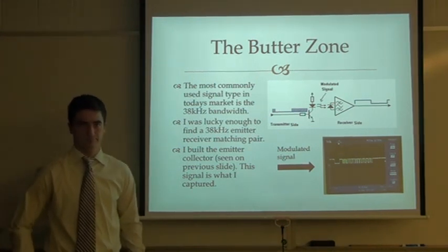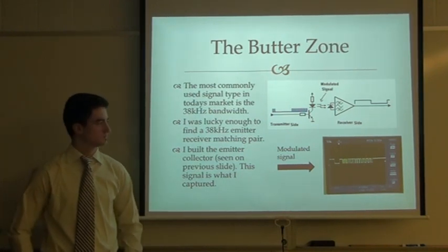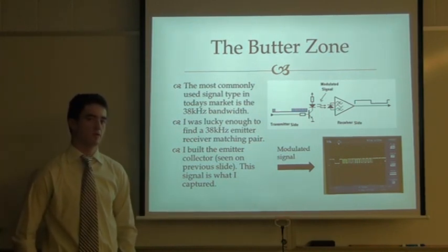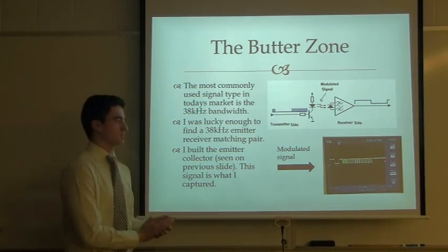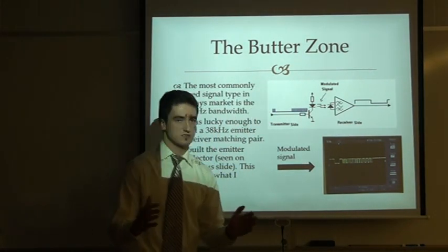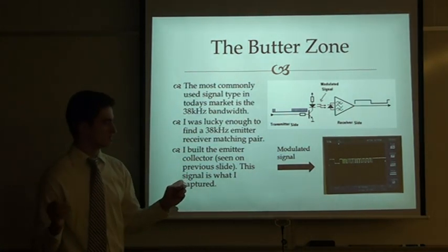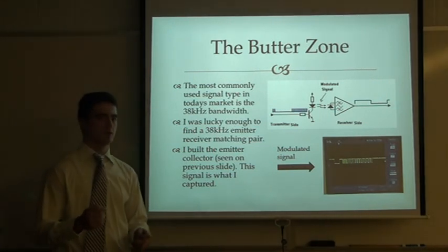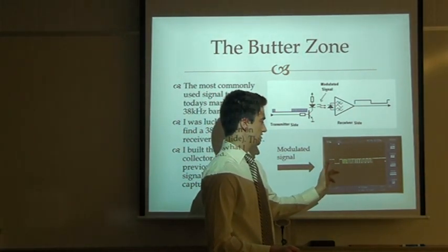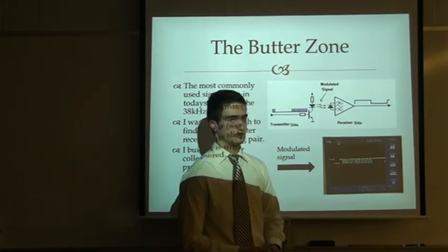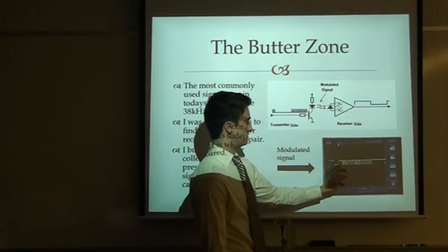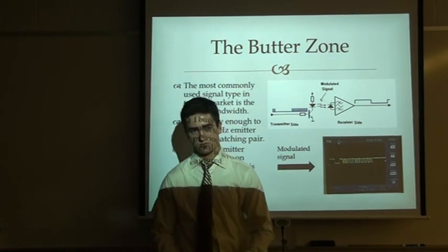So 60, 70 milliseconds is not at all related to the 38 kilohertz, right? I broke that down. Well, you said you could see the 38 kilohertz in here, but I can't see it. Well, apparently, when you break this down into smaller components, this is the entire signal. So when it's broken down into its modulated or demodulated form, these blocks of high will be independent 38 kilohertz pulses, and in the low zones, there would be an absence of the 38K pulses.